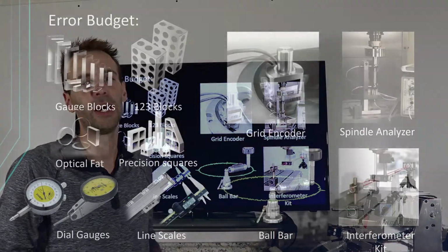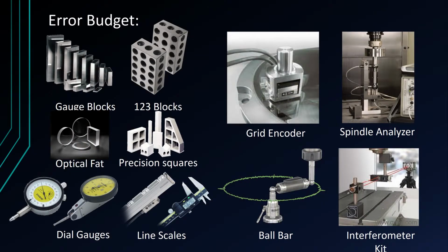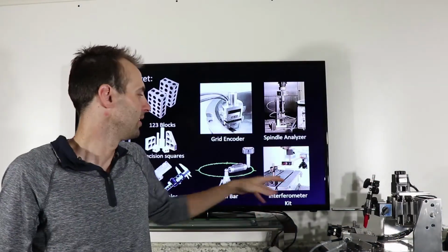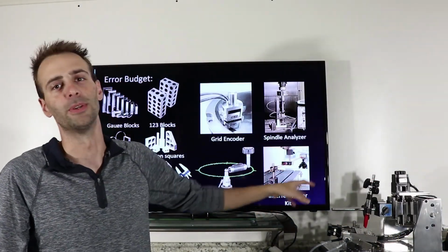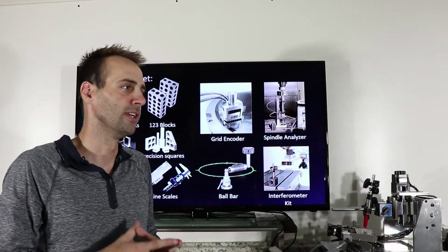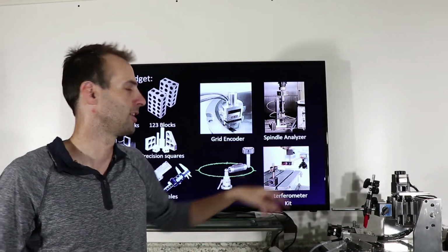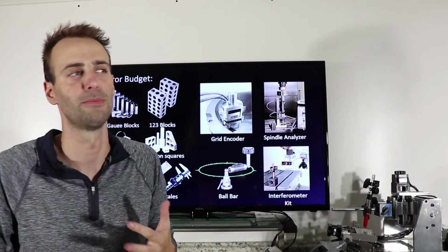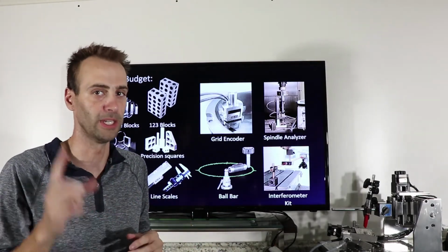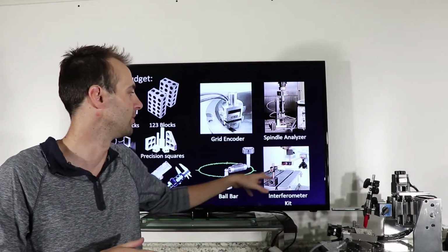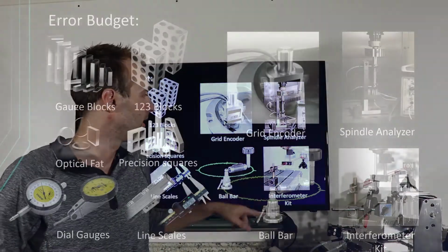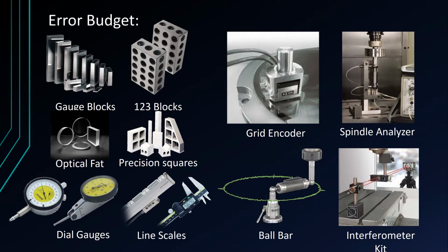And then on the bottom here, I'd say that's just an interferometer kit. This is like the staple for all initial characterization, okay? And these kits come with beam splitters and Wollaston prisms and all sorts of things that help you decouple individually all your errors out of the machine. So right now it's set up with the lasers, in this one it's even out of the machine, okay? So that's looking through the laser heads pointing through a window, probably in the side of the machine, okay?